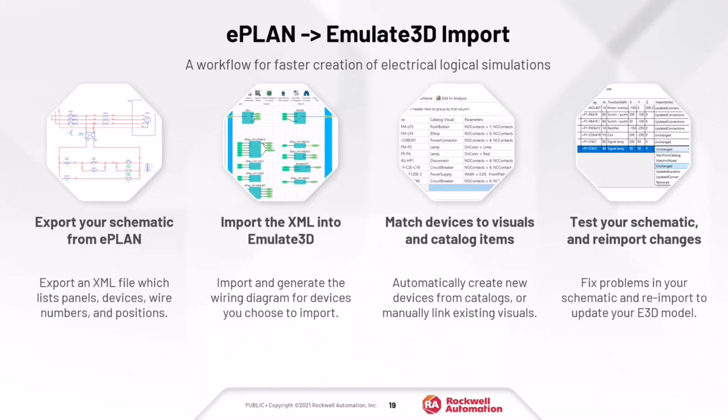If you press this button, you want to make sure that it's the right motor that's connected to it. Through the schematics, you can make sure of that, and that information is transferred to Emulate 3D. Through this import, you can also match the part numbers. We import not just the devices, but the connections of the devices, the wires, and also the part numbers. We have a list of all the part numbers in the EPLAN project, and you can map these part numbers to the Emulate 3D blocks with various different parameters.